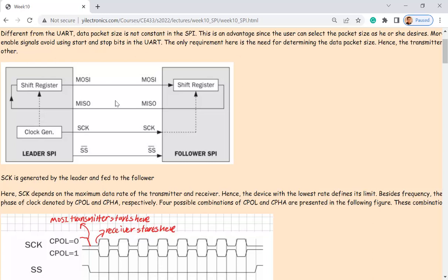Is that analog or digital? Analog. So we need an ADC. Okay, so to use the ADC to digitize it, so we got a digital signal parallel, for example, 8 bit. Outside of the ADC, 8 bit. What's next? You got a data ready, it's a byte, for example. I know it's not a byte, but the byte is ready over there. What's next? Parallel to serial converter. And actually it's an SPI module.